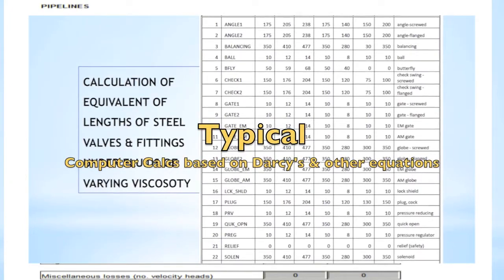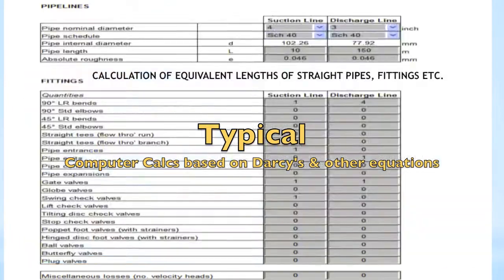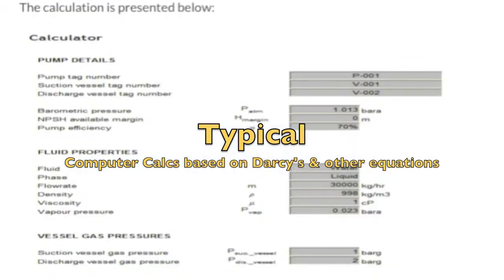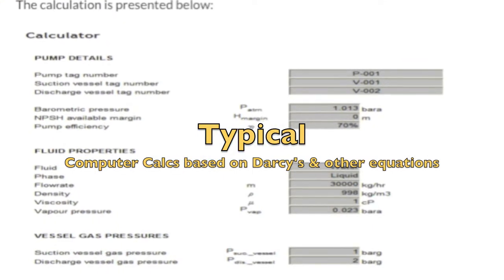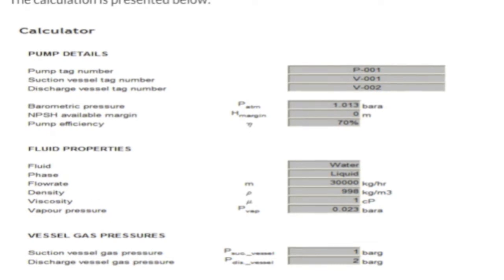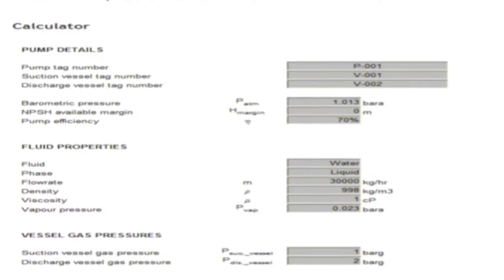The valve manufacturer gives you the pressure loss in the valve, and we just plug that into your software. Purely laminar flow is not possible in most piping systems. The flow in general will be more towards the turbulent side, and what we are doing in the design of the pipes is limiting the turbulence to manageable levels.